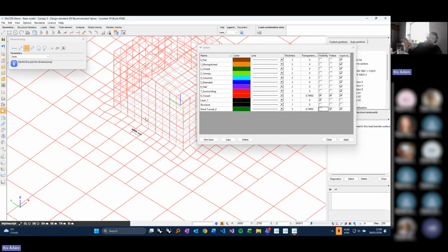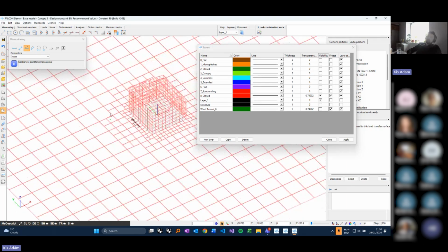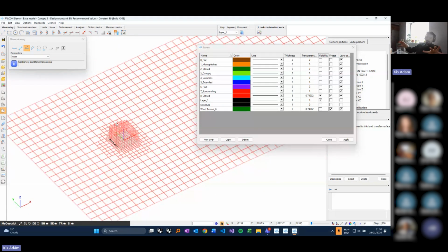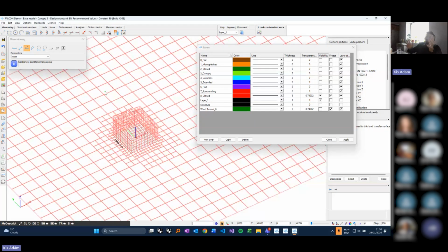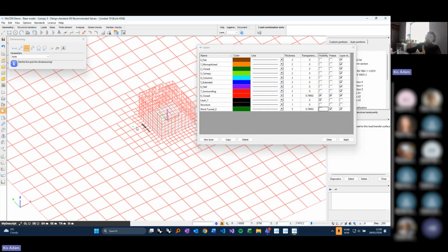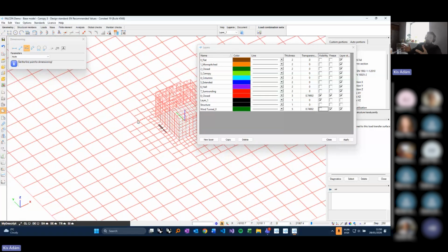And what that specific refinement factor does is that, because obviously we would have a more precise result only around the building, and maybe far away from the building it is enough to have a smaller number of mesh cells during the simulation, which means a faster simulation, we can increase the size of the meshes.